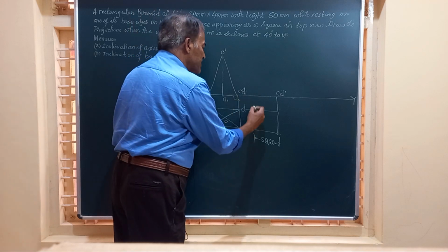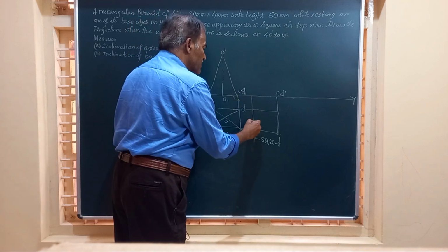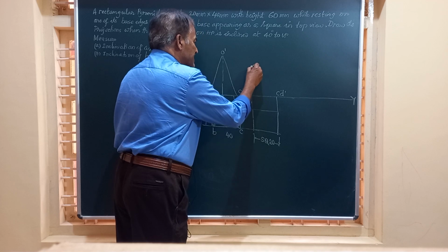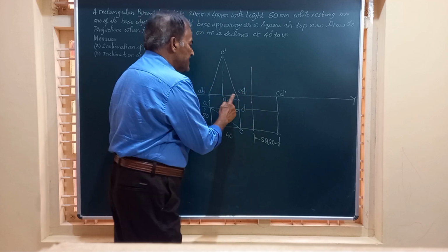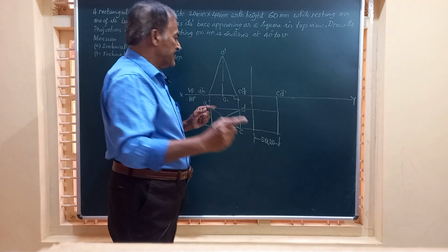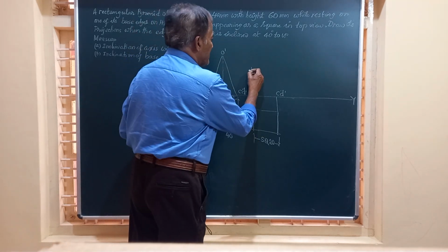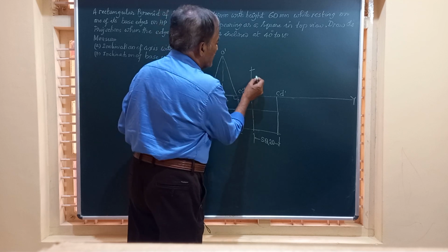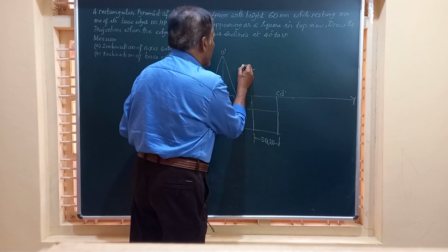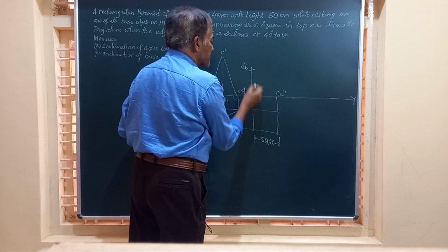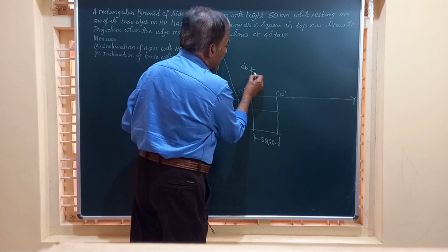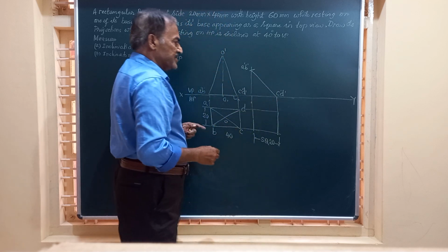And now I am going to draw a vertical line through this straight and, taking C dash D dash as center and radius equal to this 40 millimeter, I am going to strike an arc. So friend, this becomes the point A dash B dash, and you have to join that with C dash D dash.